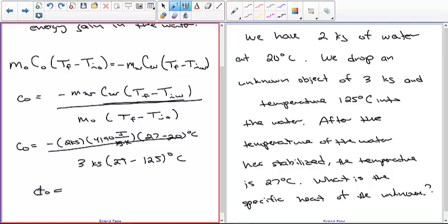Really, the only times you have to worry about it being in Kelvin are calculating the speed of sound, using the ideal gas law, or radiation heat transfer. But we're not going to get into that detail. I'm trying to think of other places where you have to have it in Kelvin. In most practical situations, you're talking about temperature differences and not absolute temperature.